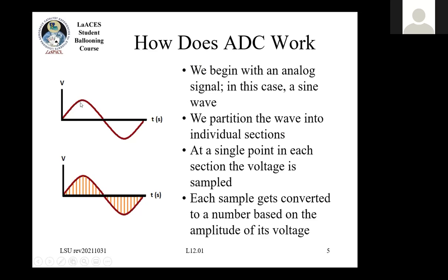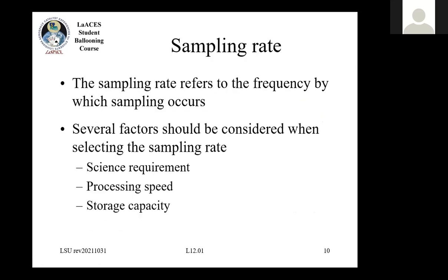Well, if I'm sampling this every single time on the peak and no other time, it's going to look exactly like a DC voltage, right? Because I'm just picking it at the same time. Whereas if I'm getting it at twice the speed, well, I'll get here and I'll get the peak, right?